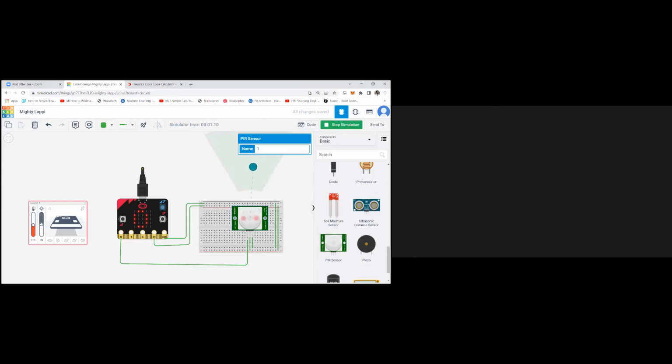So once we are in the visible area, it can detect the motion, and once we are outside, it can't detect the motion. And if we stand still in the visible area, that also can't be detected using the PIR sensor, so it will be 0. Did you all get it, guys? Sir, can you show the code?